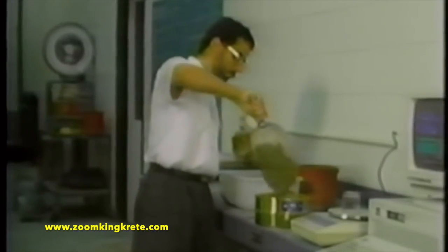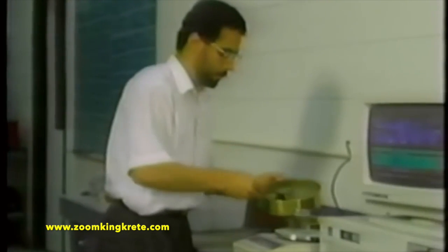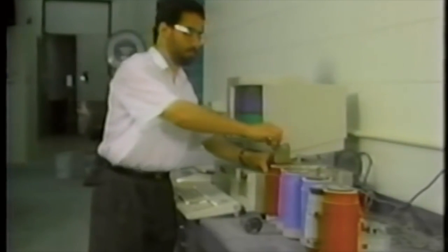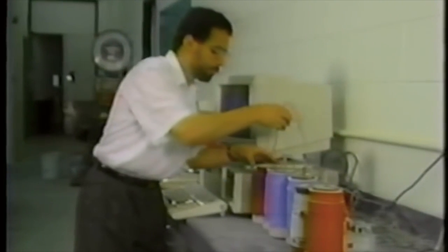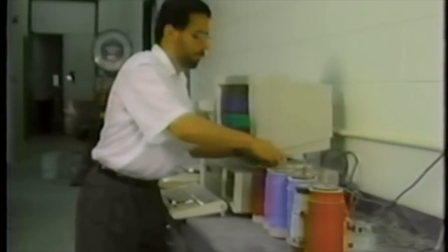Hydration is an exothermic process which generates heat through chemical reactions. The process of hydration can be easily followed by monitoring the production of heat that accompanies the reactions. This is done by sieving mortar from a batch of concrete and weighing it into a bottle which is placed into an insulated container. A thermistor is then embedded into the fresh mortar. The output of the thermistor can be recorded by a computer.